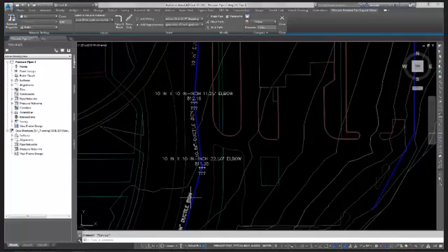So you might actually see your pipe come through the ground, out of the ground, in the swale if it's deep enough. Or if it's a hill, you may end up being 30 feet deep instead of going up and over. The hill's a little less of a hindrance than the swale, just for the fact that it's a little bit cheaper just to send your pipe straight through the hill than to have it actually follow the contours of the hill, depending on the size of your hill.